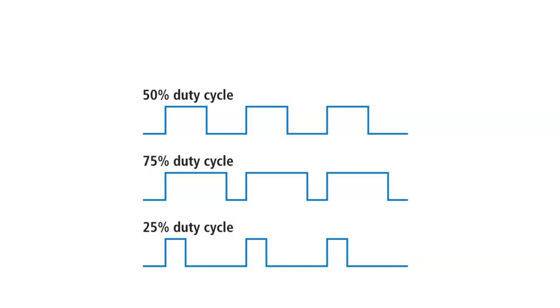In this case, we get a control, and the way we control it is by using the PWM mode, not the toggle mode, PWM mode on channel 4. The period of the waveform is set by the ARR register, and the high part of the waveform, called the duty cycle with respect to the period, is done by setting the capture compare register. So if I have CCR as 500 and the ARR as 1000, that's CCR is half of 1000, so we get a 50% duty cycle.